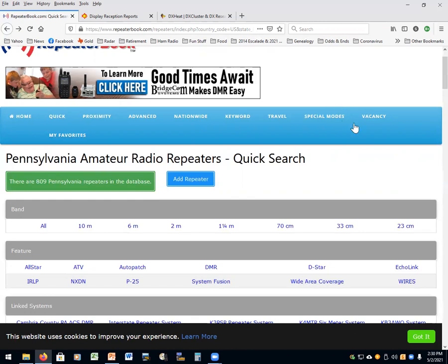So my question is, what's the cheapest, easiest way to check how good your SWR is? I got a little power bar on my HT. Would that just be the easiest way to do it? Just use the thing and see where the power bar goes? You really need an SWR meter.